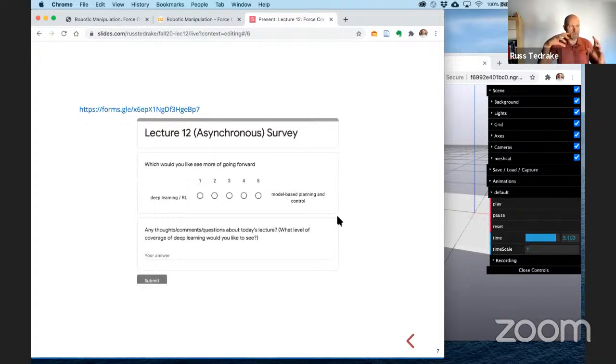So what am I asking for from the perception system? I'm just asking for the orientation of the box. I do have some numbers in there that are a rough weight of the box, but I think if we explored it, I could multiply those by 0.5 in either direction, and it would probably be fine. The controller would still work. All right. An uncertainty analysis would be the next level of maturity that we could do here, to say how robust this controller is to variations in the coefficient of friction and in the few things we've asked for from perception.